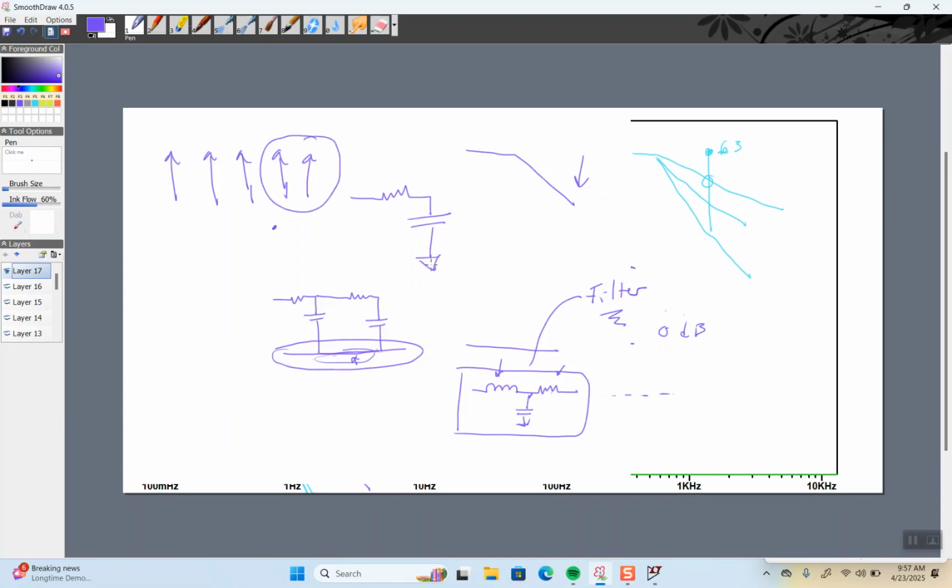All right, this is the thing. I have ground here, right? And then I have ground here. But if I put a voltmeter from here to here and ask what's the voltage, you'd say 0. No, because you've got this kind of quasi filter impedance really there. And at different frequencies, these voltages will not be the same.